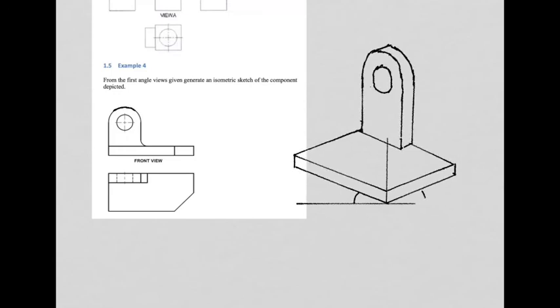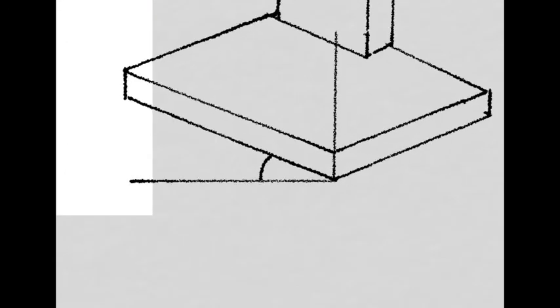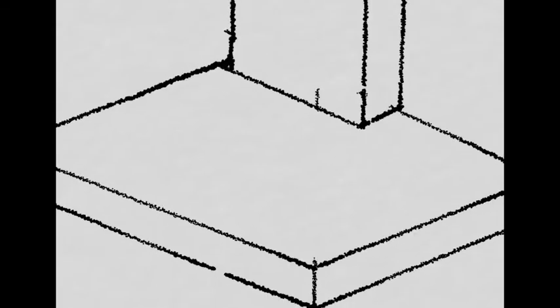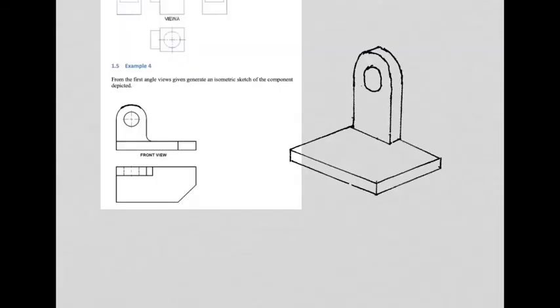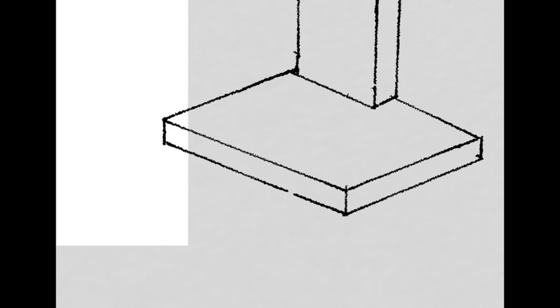Get rid of my construction lines. Where I set up my 30 degrees, that can go. This bit can go, that was a construction line. Right, two things missing. We need to chop off this front corner. So let's estimate where that cutoff is. Once you've cut it, you would have a hard line there and a hard line over here. And of course you would have the hard line where the cut was. And we can erase the bits that are gone now. Something like that.